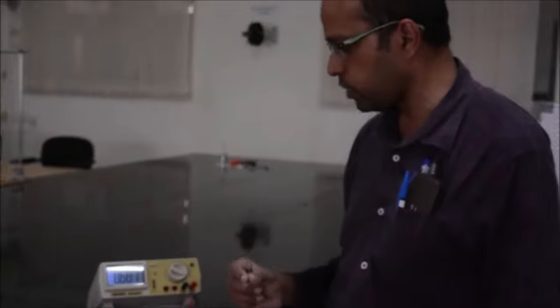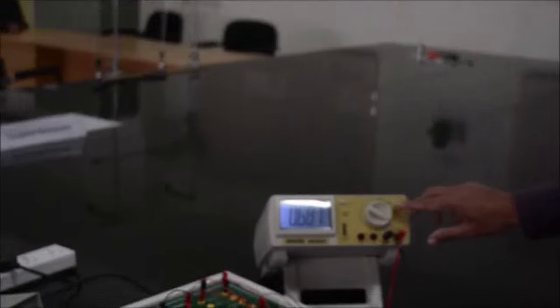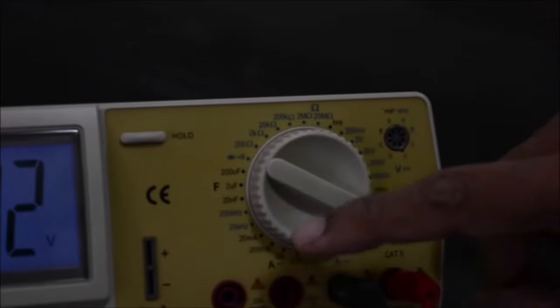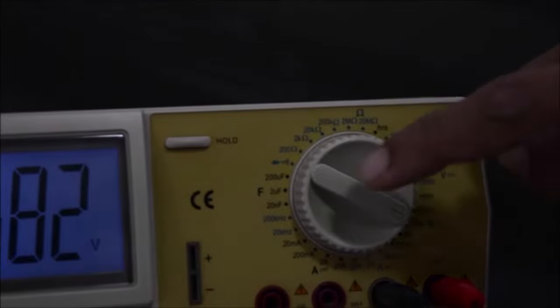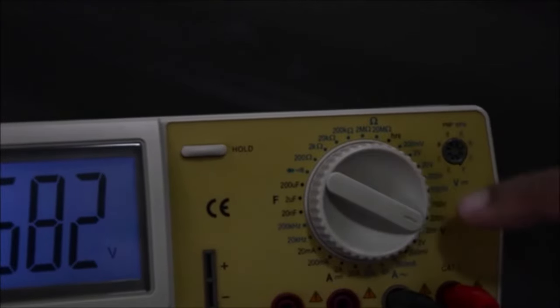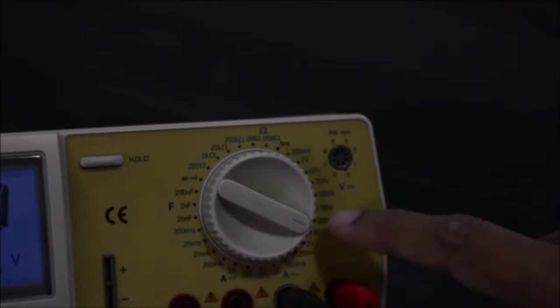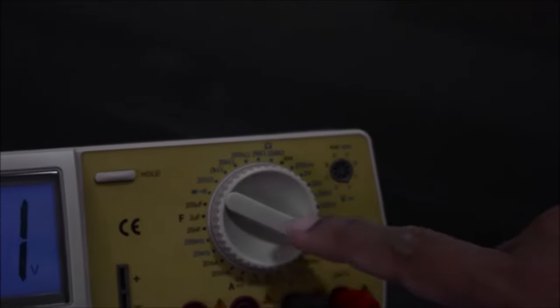There is one more thing which you have to keep in mind while doing an experiment, especially when you are encountering a new setup. In the voltmeter, you might see that there are some knobs here. This is a multimeter actually, okay, which means you can measure various things like resistance, voltage, current, and so on, and even capacitance. So you will have to set the knob. Make sure that the knob is set for measuring a voltage and an alternating voltage. It can also measure direct voltage, but you have to set it here.